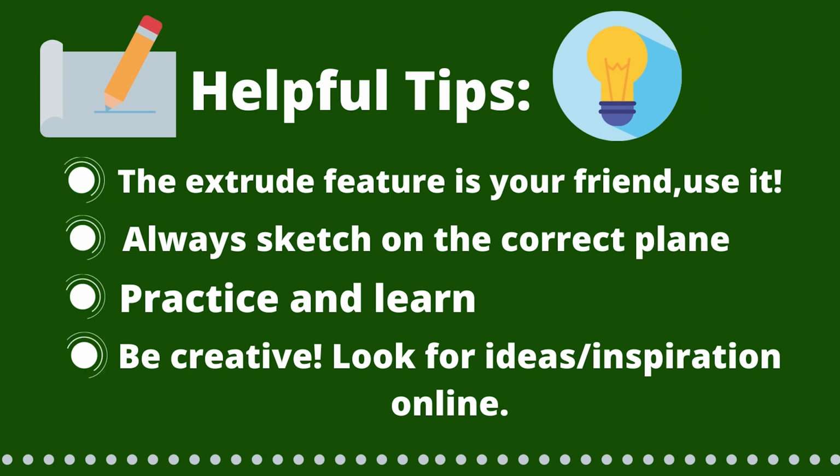The next tip. Always sketch on the correct plane. If you sketch on the wrong plane, you'll put the feature on the wrong place. This may be confusing at first, but you'll get used to it as you go.